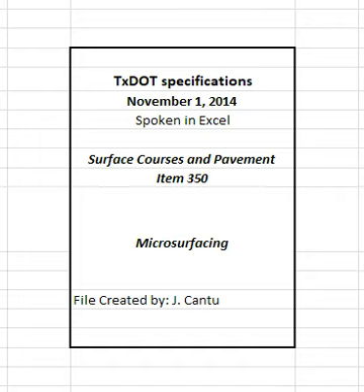For sources not listed on the Department's BRSQC, build an individual stockpile for each material. Request the Department test the stockpile for specification compliance, and, once approved, do not add material to the stockpile unless otherwise approved. Allow 30 calendar days for the engineer to sample, test, and report results for non-listed sources. Do not combine approved material with unapproved material. Include the amount of mineral filler added to the mix in determining the total minus number 200 aggregate fraction.